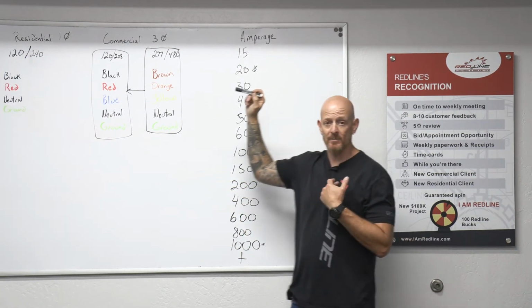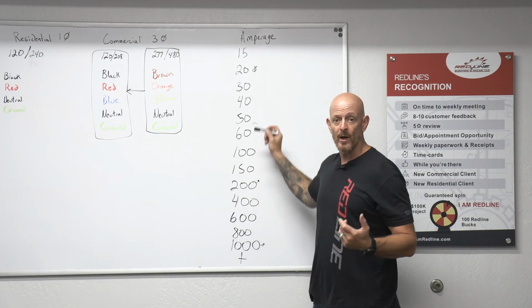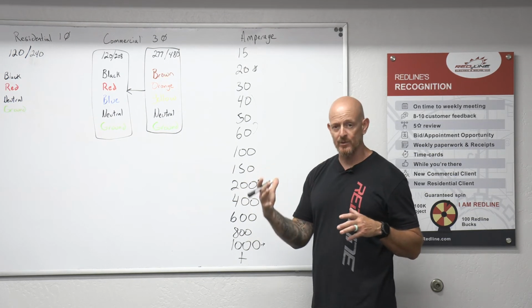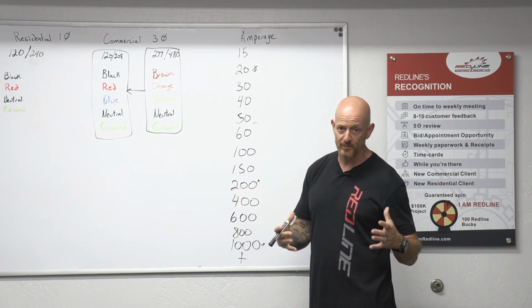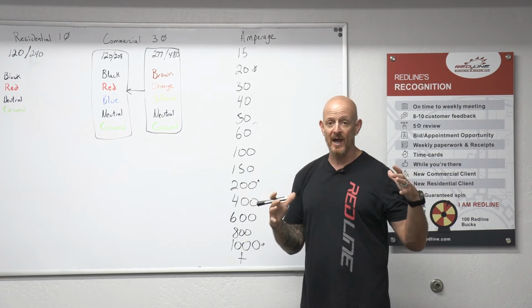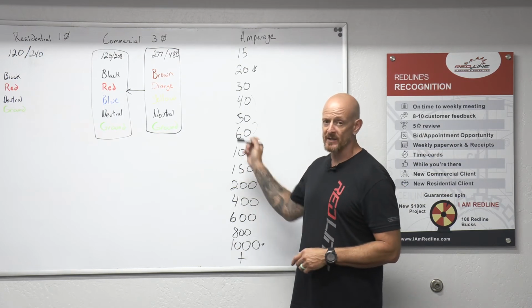But when we're estimating, a 12 gauge wire is going to cost reasonably less than an 8 gauge wire. So we use the gauge of wire to determine what conduit we need to run, what overcurrent protection we need. Do we need to have fuses? There's a lot of things that we need to have sized for that overcurrent protection based on the amperage.